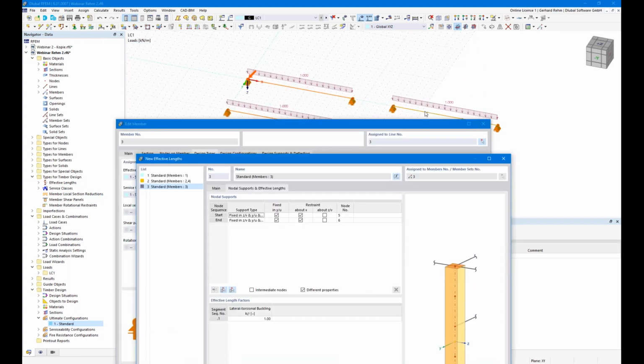And with analytical solution, we assume the bending moment is parabolic, but in between these 2 nodes, the distribution is nearly constant. And when it's constant, then the factor is 1.0 according to Eurocode tables. It's an assumption, but it's actually a good assumption. It can be used, and it's common to use it in practice.